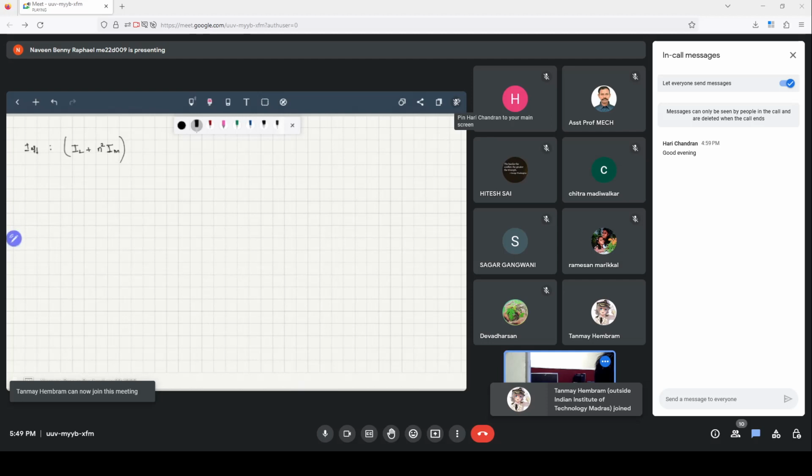The derivation of this goes by understanding the principles of how a gear shift works. If you have a gear shift, then the power is the one thing which is conserved. I mean, we have conservation of energy, and if energy is conserved, that naturally means power is conserved. We know power is torque multiplied by angular velocity.